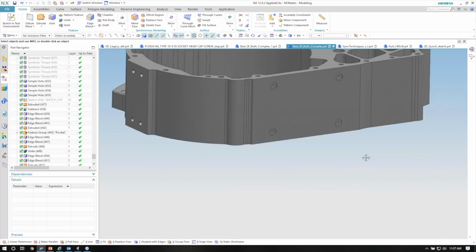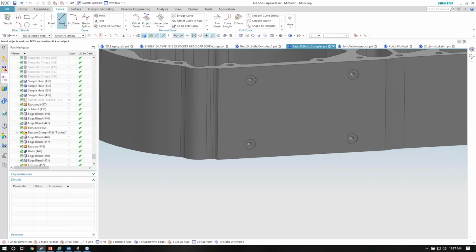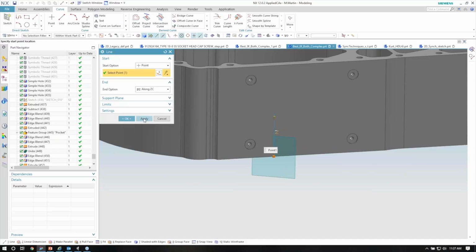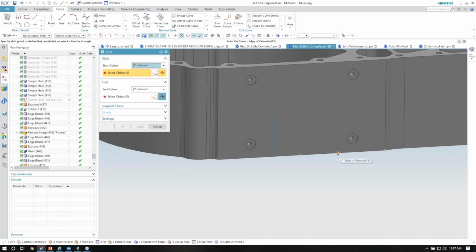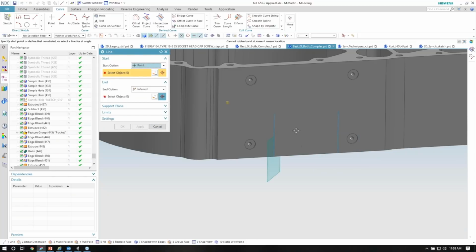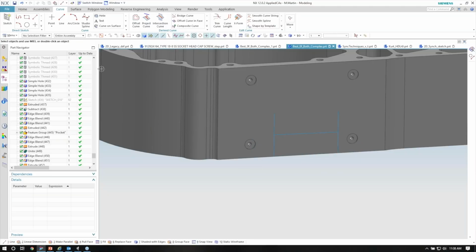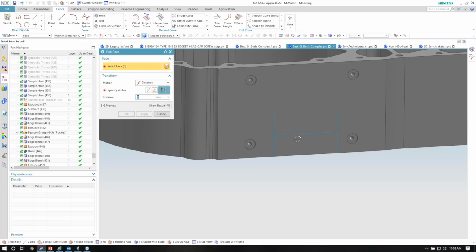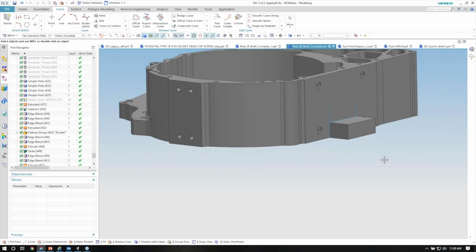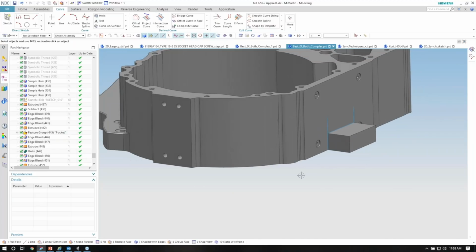So I'm going to do it again on this face over here. I'm going to go to my curve tab, line, pick a point on that edge and let that just kind of go up in Z, so I know it's a pretty straight line going up. May as well use it if I got it. Apply that and let it snap to the midpoint there, and maybe even the midpoint over here. And again, I'm going to use a pull face with region boundary right there. Pull it out to a value, and again I can straighten things out and put a dimension on there if I like.